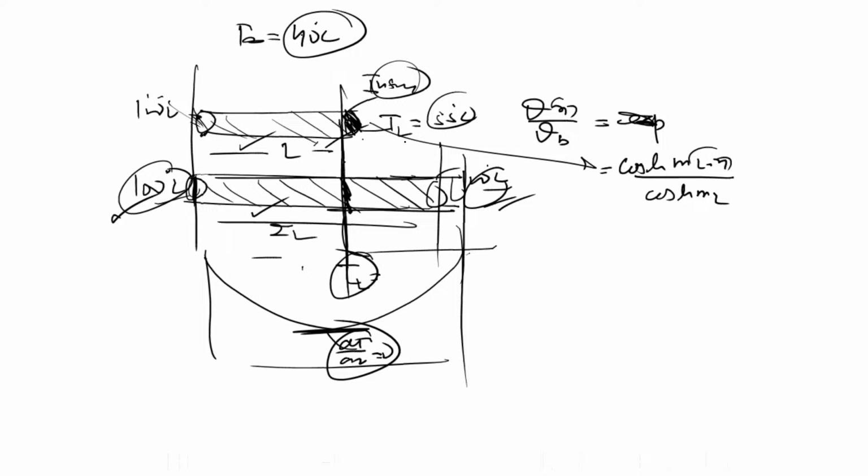So my dear student, the same thing applies up to this L length. Theta x, they're asking what temperature, yeah? So m is the same. What is m? m is the square root of hP upon A_c K. P same, perimeter same, A_c same, K same, because same material, same diameter. So m is the same. And at x equal to L, the temperature is known to you.